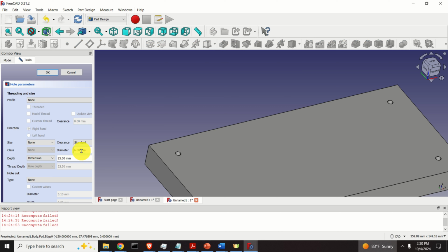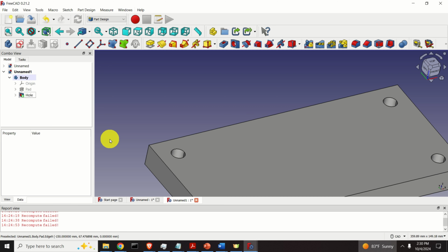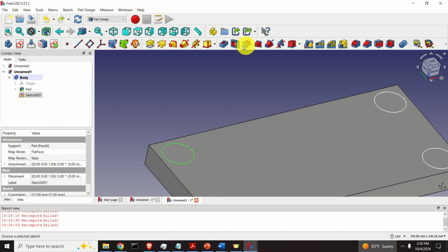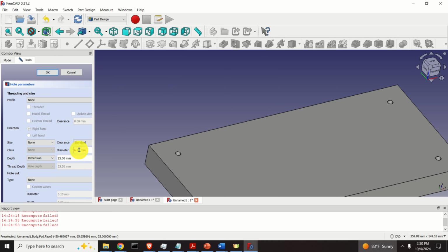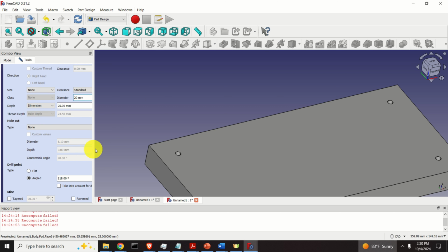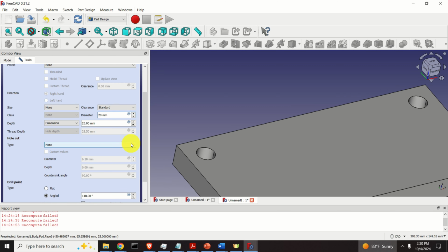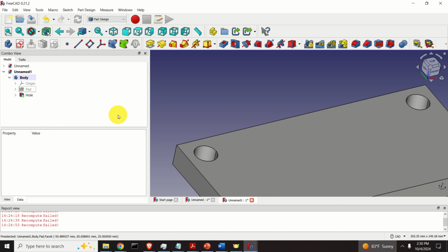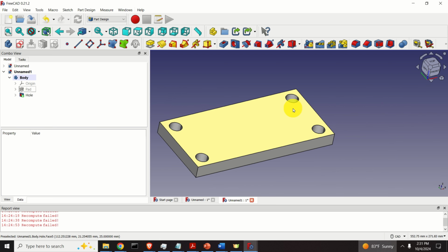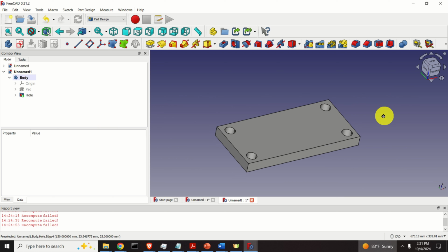Here, the issue is that you need to specify the diameter. We don't care about precise diameters. For example, let's select 15. This might be too small. Let's press Ctrl Z. Let's repeat this. Click here. Then again, here to create holes. And let's select, for example, let's see, what do we want? Like 20? Is 20 too much? Let's see. Maybe a little bit more. Let's go with 25. Okay, 25 is good. Press enter and voila, here are the holes.